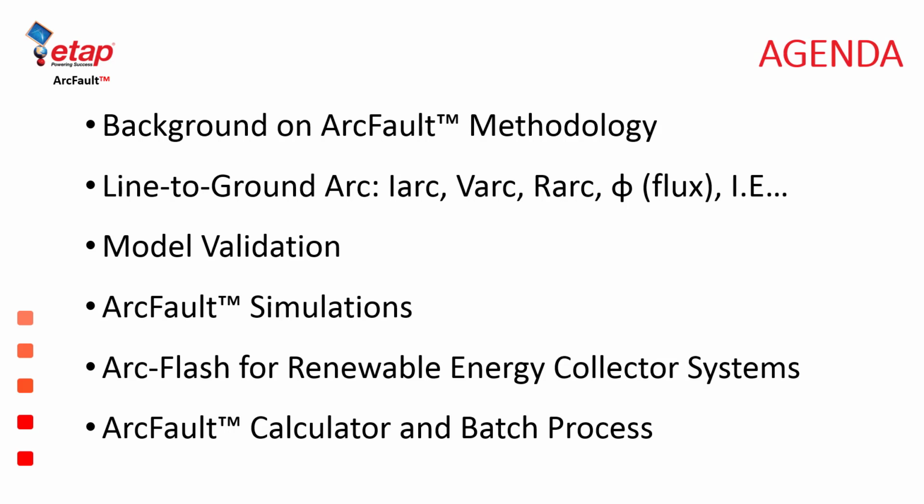We will discuss the model validation and development, plus go over some of the assumptions that were made for its creation and use. ArcFault is not simply a static application, but it's a fully integrated product within the ETAP ArcFlash family of products. And we will be able to observe simulations of arc faults placed at different voltage levels and equipment types. This will include single-phase arc faults, line-to-line arc faults, or three-phase arc faults.